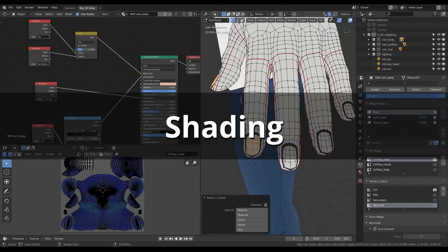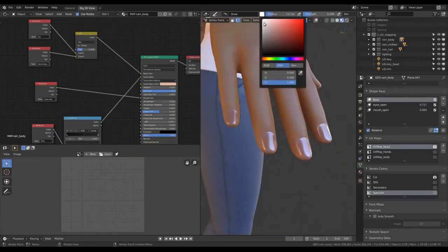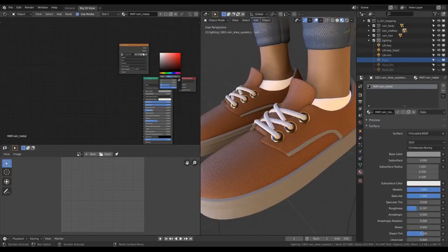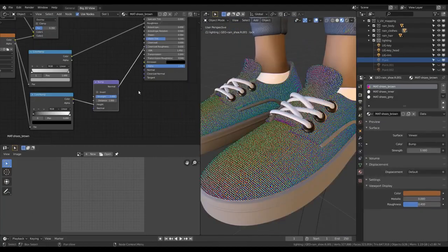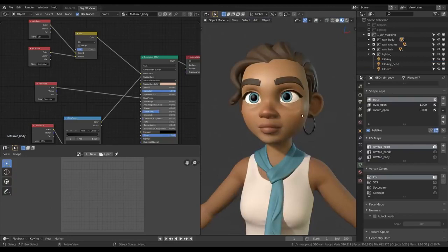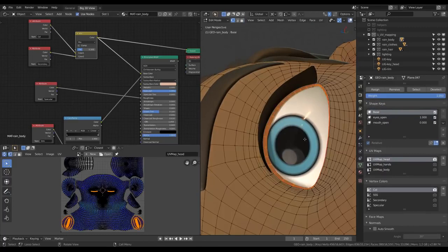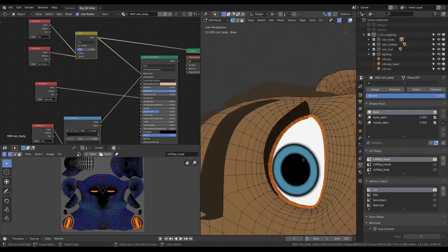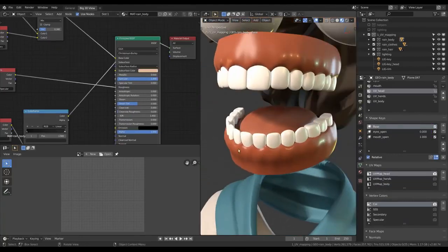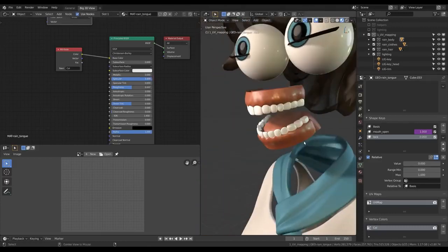The other most used inputs in the shaders, apart from the base color, are roughness to define the glossy shine or the lack thereof, metalness if the surface is metallic, and normal to add fake high-frequency details that we didn't model in already. If you want parts to be transparent, like glass or ice, you can use transmission, and to just make them fade away or completely disappear, use alpha. You can also use specular to tone down the glossy highlights, but if you want to have it really realistically accurate, increase the roughness instead.